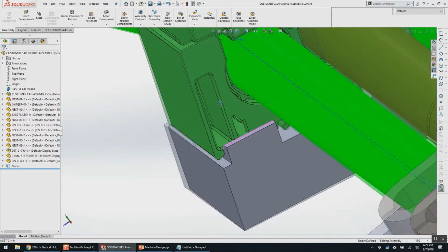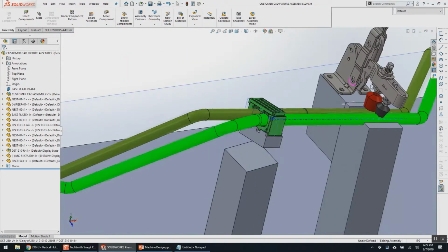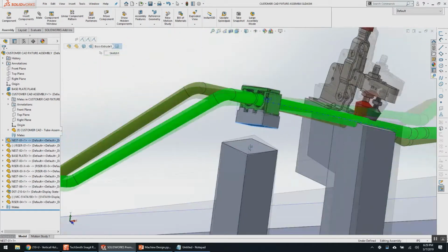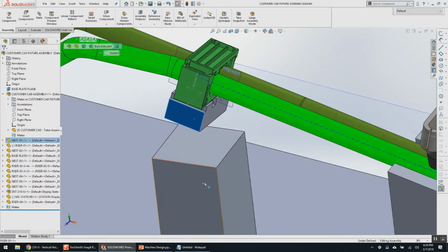I don't remember what was happening here for positioning it or clamping it or checking it. We'll pretend that we have to clamp that as well, so we've got our handy clamp already. Now the problem is going to be fixturing this to the plate because it's at a double compound angle. I'm not going to be able to just cut a one-side angle on this, which is easy for machining. I don't want to do two-side angle because that's difficult.